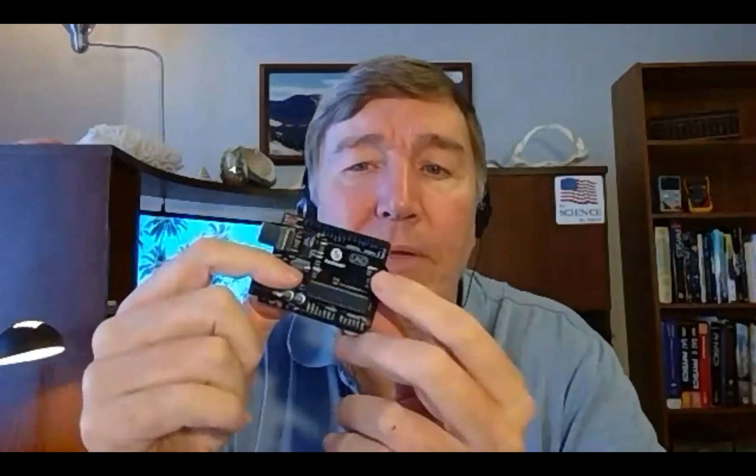And in fact, this is one thing that we should talk about. Now's as good a time as any. If we're working with real Arduinos, you have to be careful because you can easily destroy an Arduino. If you hook up an Arduino to something that pulls a lot of current out of it, you can destroy the Arduino. The maximum amount of current that you can put out of any one Arduino pin is about 20 milliamps.